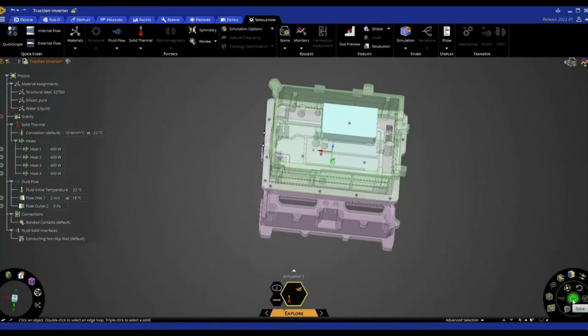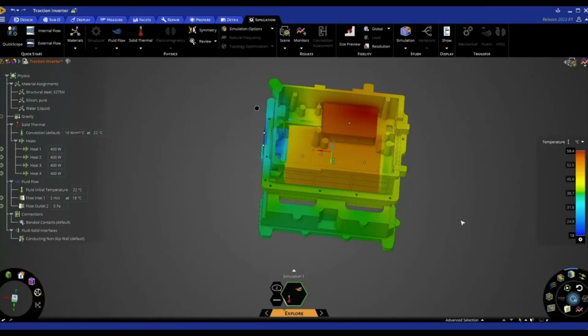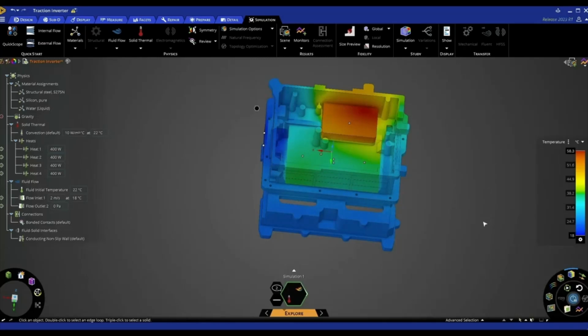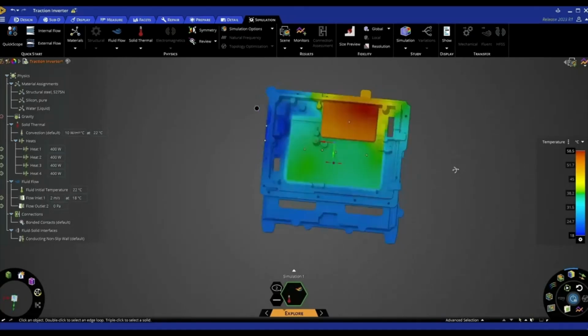So that's just something to be aware of, but this is going to show steady state. I'm now going to hit the solve button, and again in a few seconds we're going to start to see some results, and hopefully our max temperature should have quite drastically decreased. We can see now that we're looking at around 60 degrees. It hasn't fully solved yet, but it has now. So we're looking at around 58.5. So we've come down from 430 degrees to 58.5 in terms of temperature.